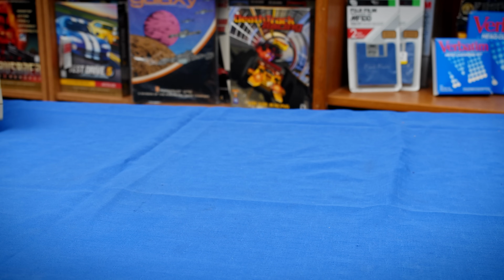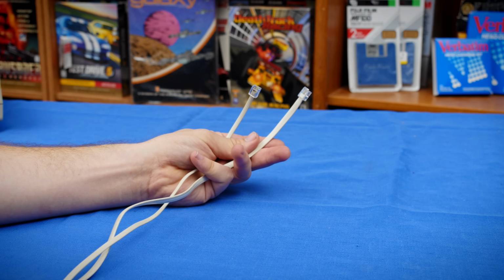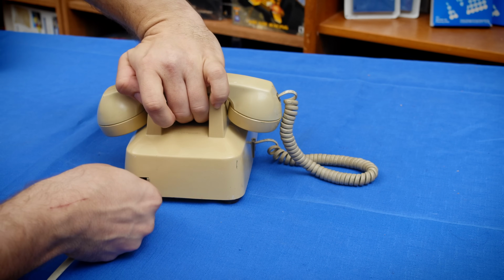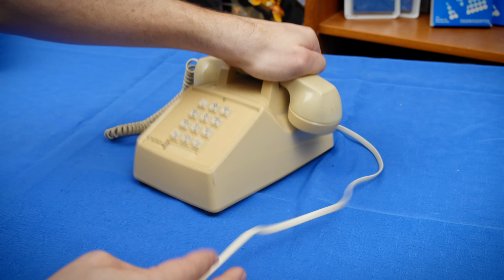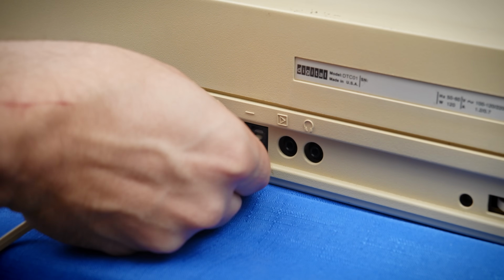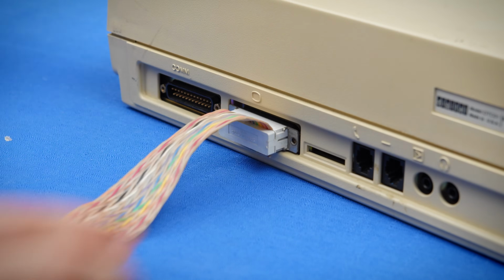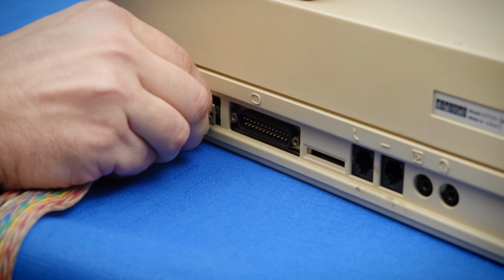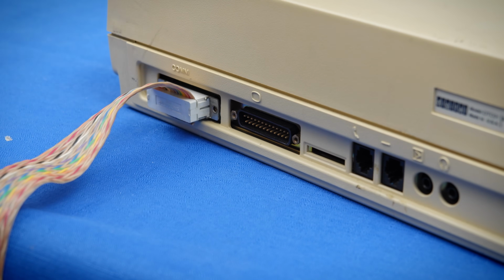In this setup, I have 2 active phone lines that are able to call each other. One I'll connect to a touch-tone phone, and the other I'll put into the line phone jack of the DTC01. But I also need to change to using the host serial port instead of the terminal port. The host serial port operates differently than the terminal port and is better suited to the kinds of larger pieces of information that you would want to convey over the phone.